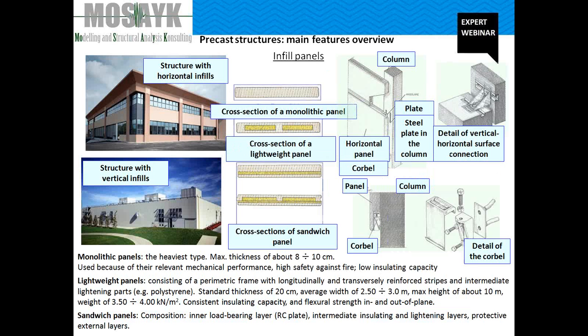Non-load bearing facade elements are intended to contribute to the architectural effect of the construction through shape, color, texture, quality. Thermal and sound isolation is achieved by the insertion of light, expanded foam or mineral fibers materials into the facade. The orientation of the infill panels can be important in the seismic response of the structure.